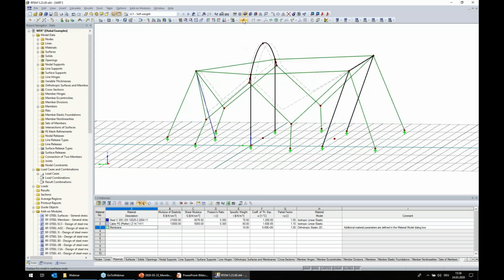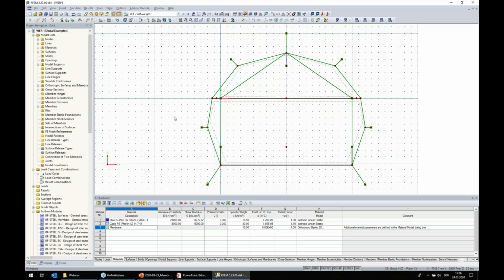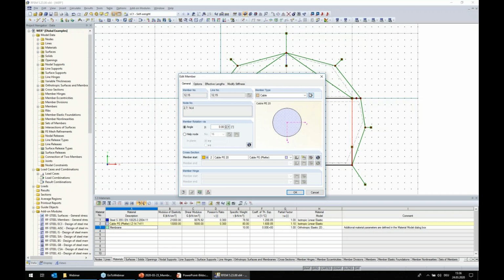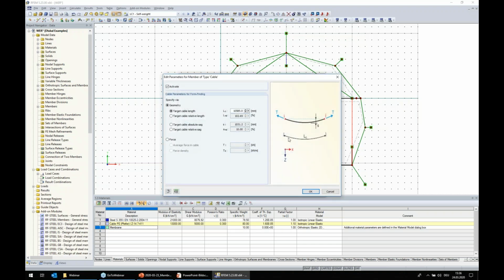At first, I would say for the cables, it's helpful when we do it from top view. So you see, this was our basic primary support construction, which was only here to support the frames without membranes. So I define for these cables, here the cable in between the frame, mid, in the middle, and in front, here in the settings of this cable, a small force, nothing big.